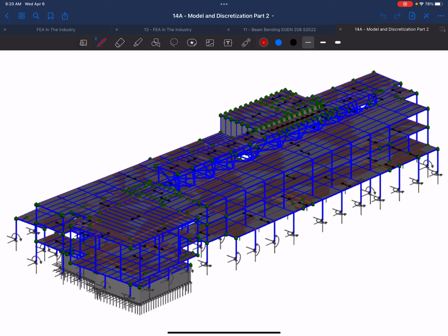Yes, for sure. And the benefit of this is, if you have an architect that's changing stuff, or they want to shave some beams, this makes it pretty easy to go through an iterative process instead of erasing and redoing your hand calcs every time, right? It's like, oh, you want to change this beam to a W21 because it interferes with a duct. I'm just going to go in the model, change it, it's going to change all my calculations, and then I can just print it off once, so that they can go to the city and get a permit.